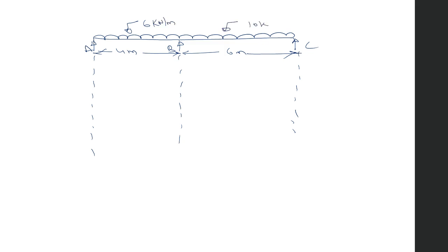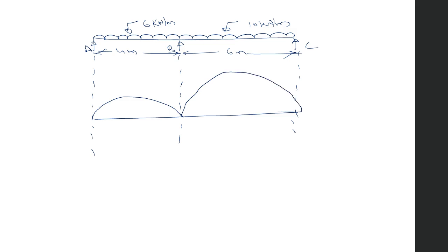This is the given data already known. Now draw a baseline. On AB, a parabola that has 12, and on BC this is a parabola, and the value calculated is 45, and this is 12. On support A it is 0, support C is also 0. At B we get 31.8. So this is the variation, 31.8.